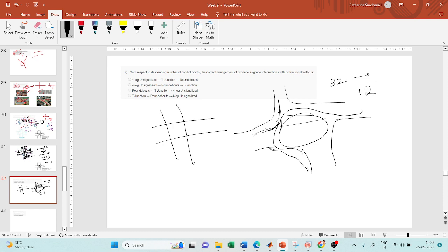Okay, so you provide a roundabout. That is one option. Other option is easy. You provide a signal so that you will not allow vehicles traveling in different directions to travel at the same time. So you're reducing the conflict points completely. Okay, we will talk about reducing conflict points in signal sections later. So first, you can provide roundabouts, you can signalize an intersection, or you can provide a channelization.